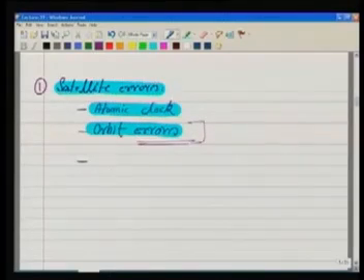As well as we discussed, the ephemeris data is collected from ground stations. These satellites are observed from the ground station, and any change, any perturbation in their orbit is being recorded. So in that recording process also there are errors. So all these errors are finally going to be introduced or being propagated into our final coordinate.